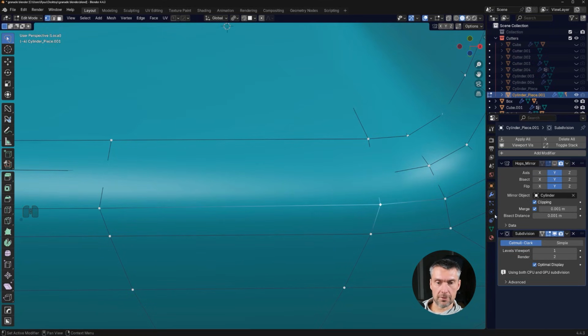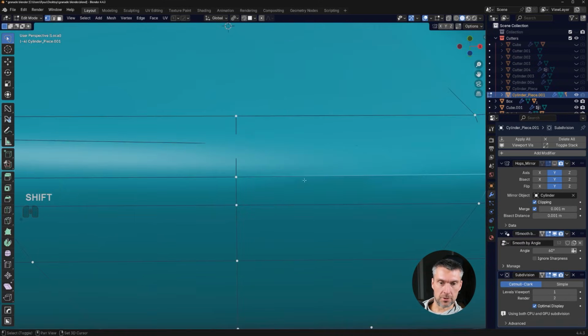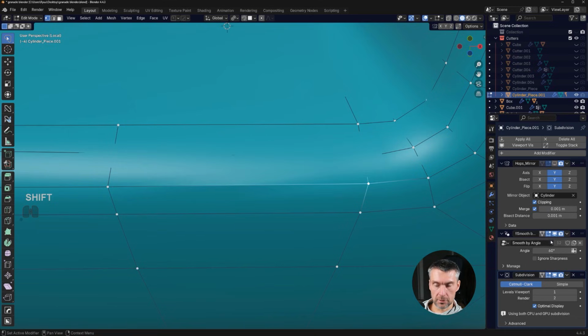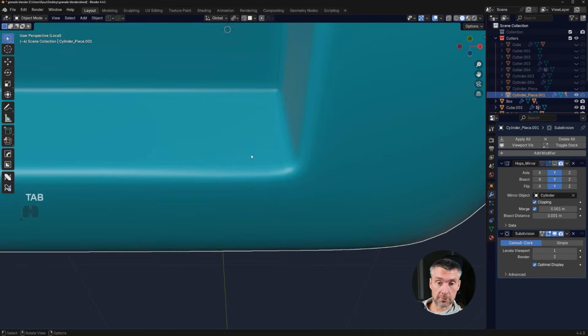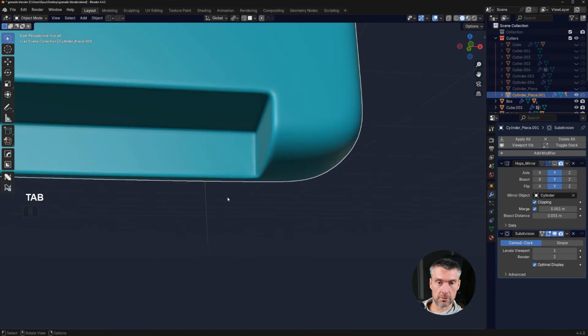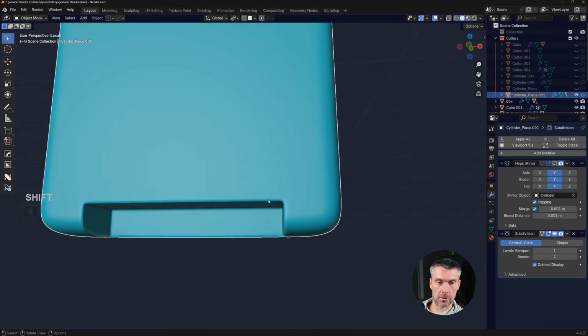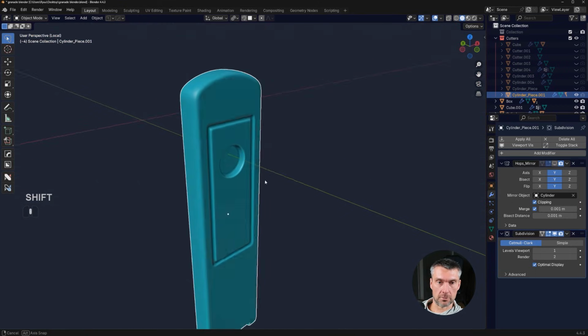Yeah. Never use auto smooth on your mesh because that's what's gonna happen. It's gonna start catching angles that are close to 60 degrees. If I set it to, like, for example, 80, it's gonna be fine, you see. When you're working with HardOps and Box Cutter, always remember to remove smooth by angle from your mesh because it's gonna cause issues, okay? So, you know, and there you go. That's how you would normally fix this to make it clean, okay? If, you know, the police are gonna chase you, all right?